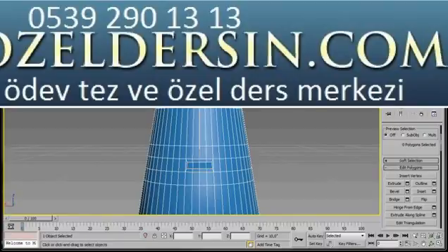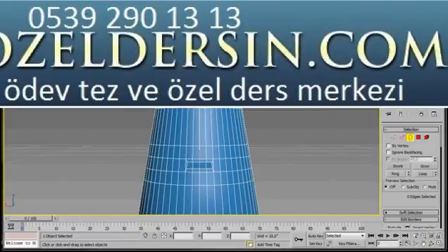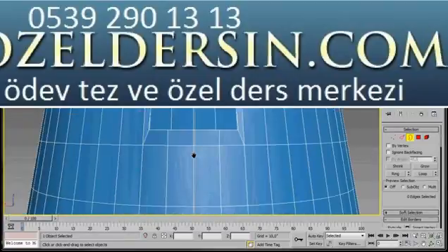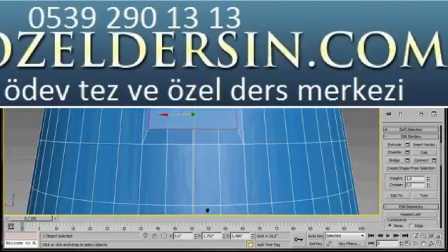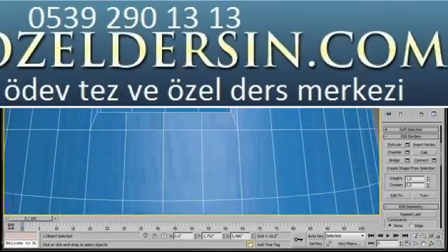Now let's go back over to the modify list, and we're going to select border. I'm just going to zoom in, and we're going to click on the border. Then we'll come back over to our panel and click on cap. We'll do the same here. Select border, come back over to the modify panel and click on cap. Now we have just one large polygon. It's going to be a lot easier now for the next step.